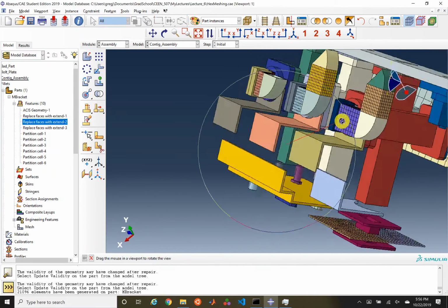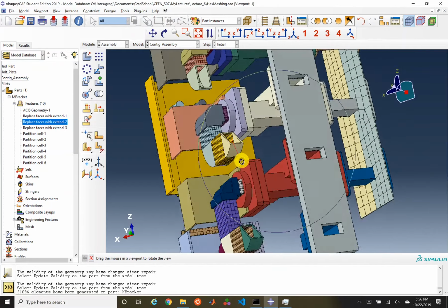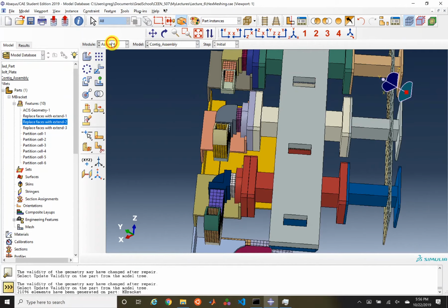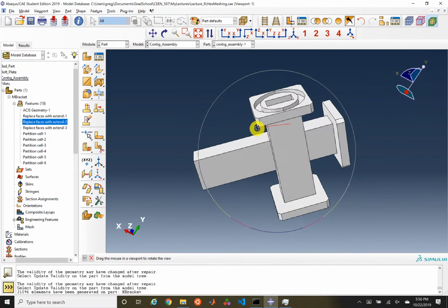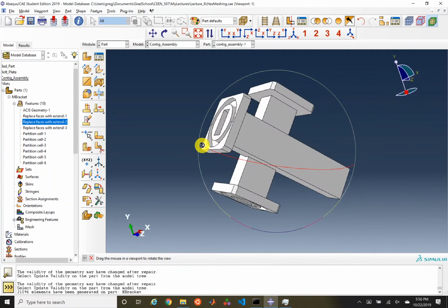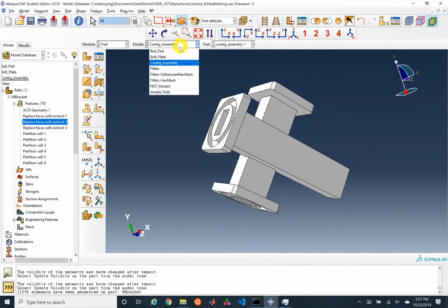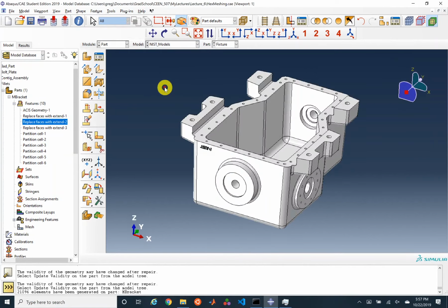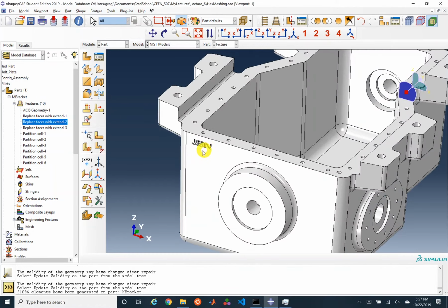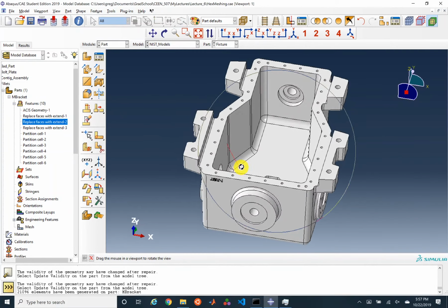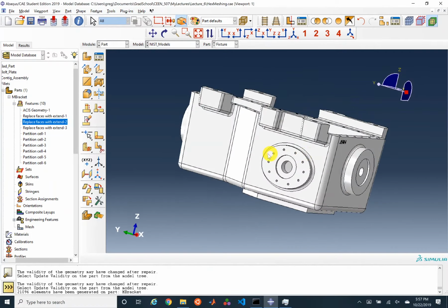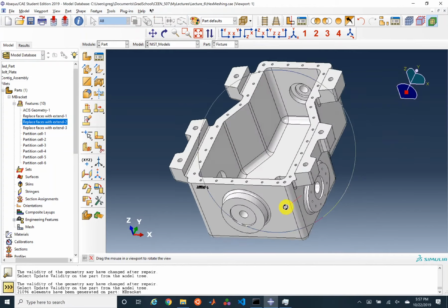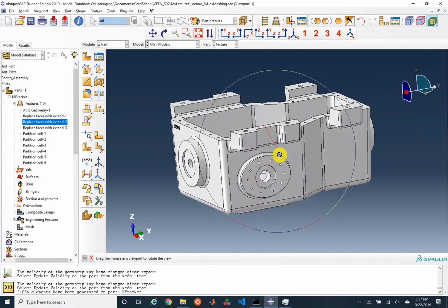But some of these parts are very easy to mesh. But then a few parts that are at least repeated, let me provide you some practice. So like this part, for instance, to try to put a hex mesh on this. So you can choose to mesh this contiguous assembly, which I think is probably going to be the easiest model to mesh. There's also the NIST models that you can choose to mesh. And this is probably the most difficult geometry to mesh, but I do want you to at least come through and on this geometry do a defeaturing run through.